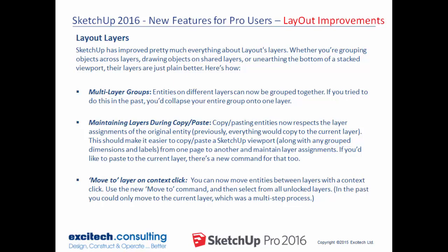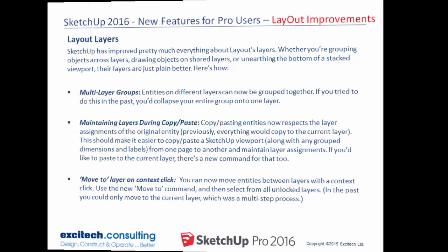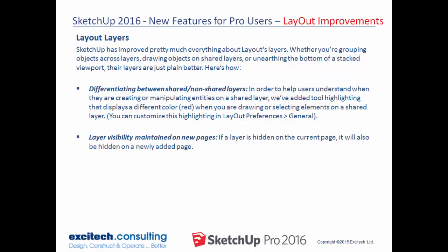I'm just going to read the bullet points. So multi-layered groups, we've got maintaining layers during copy and paste, so basically they stay assigned to the original layers. Move to, so there's an icon for that. Differentiating between shared and non-shared layers, and also layer visibility maintained on new pages. So a lot of new features there with the LayOut layers, definitely worth having a look at.